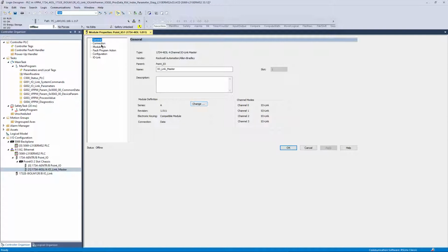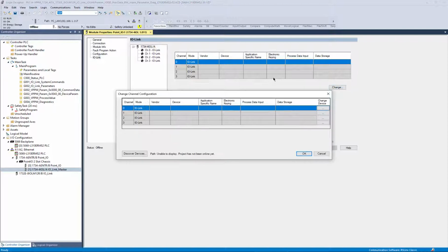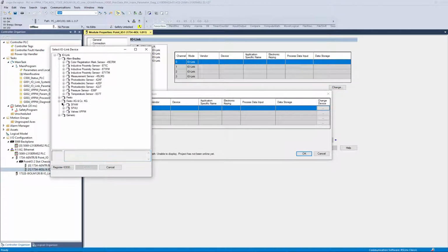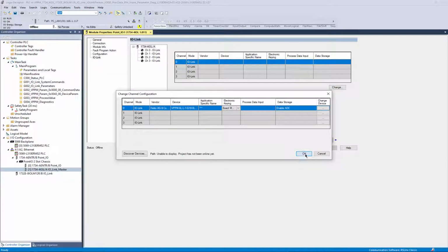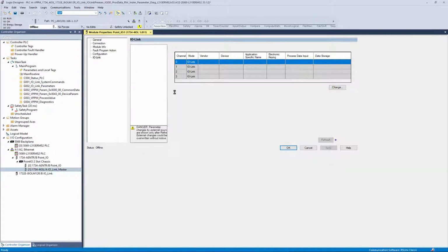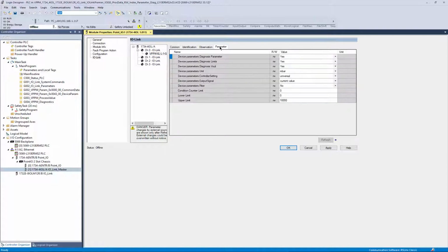And when I go into IO-Link and I want to add a device here, you select the device just like you did in the other one. Same exact device, hit OK. The fact that I want to point out is that enable ADC is not even an option. It's on all the time. In older firmware and software, this didn't even really pop up at all, and when you navigated to the device, you automatically had these tabs here offline.